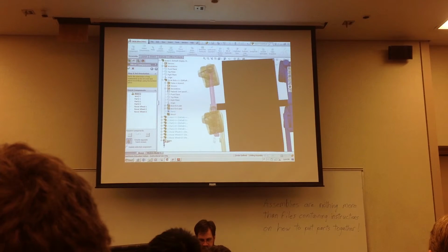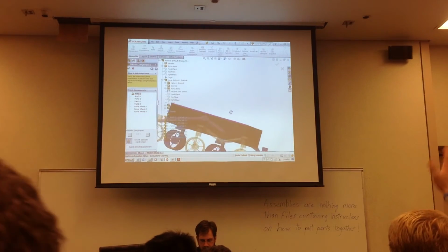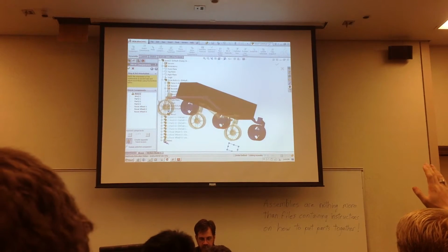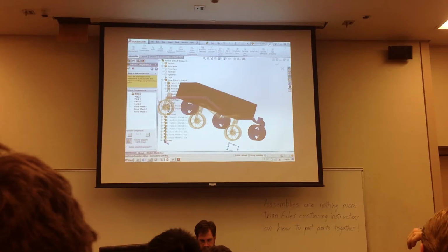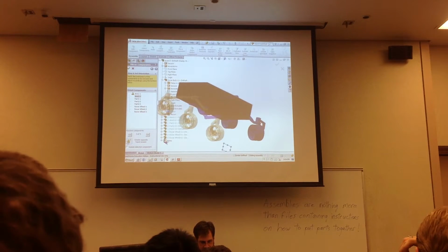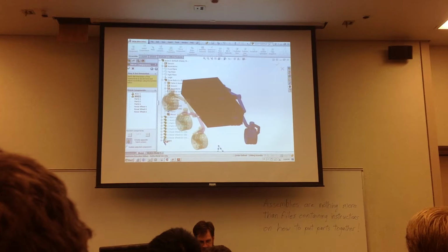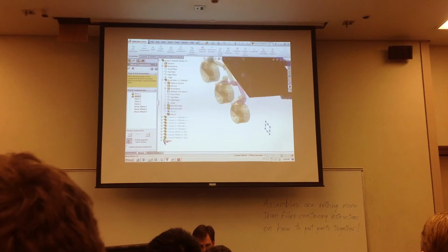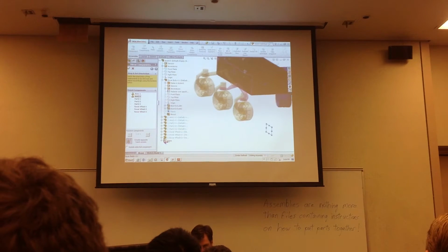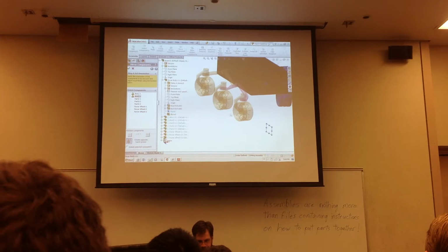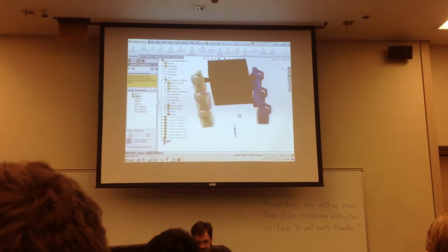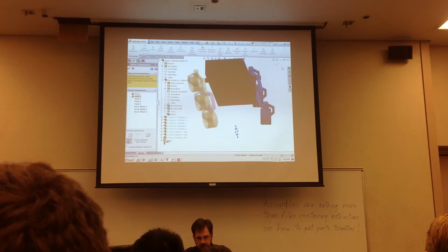Okay, it gives me the correct mirror component. We want to do the same thing with arm 2 here, because that one's backwards. So select arm 2 and say create opposite hand version. That flips over to be correct. I believe all the other components mirrored correctly. Okay, so the preview looks correct, and we're ready to go to the next step.